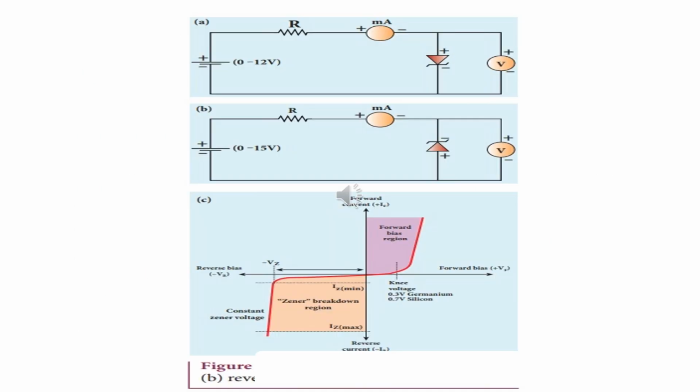Zener breakdown is observed in the Zener diode having Vz less than 6 volt. When a reverse voltage is applied to a Zener diode, it causes a very intense electric field to appear across a narrow depletion region. Such an electric field is strong enough to pull some of the valence electrons into the conduction band by breaking their covalent bonds. These electrons become free electrons which are available for conduction. A large number of such free electrons will constitute a large reverse current through the Zener diode, and breakdown is said to have occurred due to the Zener effect.